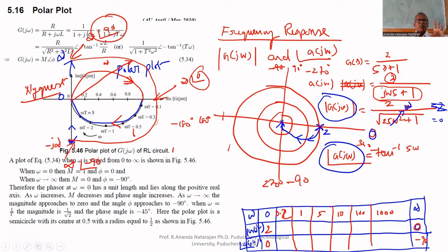What is the polar plot? If you substitute only the positive imaginary axis in the transfer function and get the plot, then it is called the polar plot. If you plot for the negative imaginary axis also, then you get the complete plot. The only thing pending is to draw the circle whose radius is infinity and the angle alone varies. That is nothing but a point at the origin. So if you combine all these three, then it is called the Nyquist plot. We can call the polar plot also a Nyquist plot because it is part of the Nyquist plot.